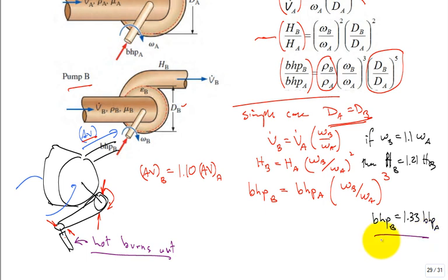Is the brake horsepower to make it go only 10% faster? Isn't it 10% more? Maybe that was a perfectly sized 5 or 50 horsepower motor, but now you are asking it to do a lot more than a 5 horsepower motor can do by just changing the pulley. And it runs a little bit because the motors will take an overload.